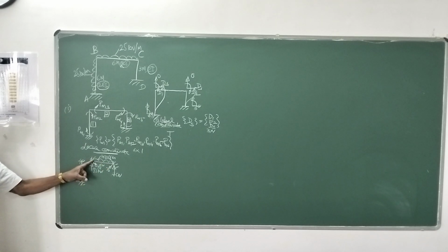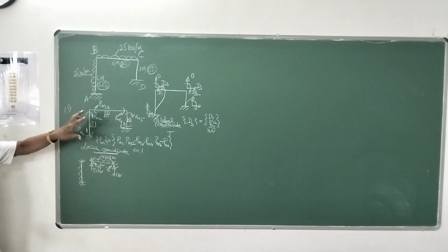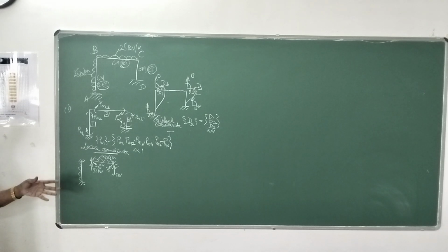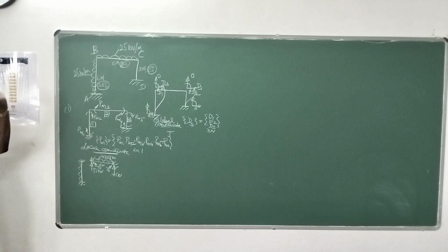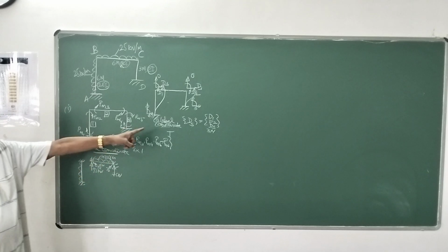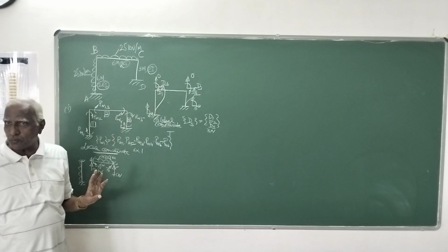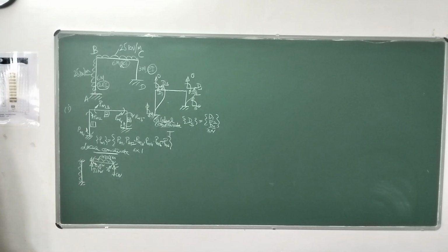So now we got the equivalent joint end reactions. So this reaction, you have to reverse its sign, as I told you in the beam problem. So here also we have to reverse its direction. That will be the equivalent joint load, and that equivalent joint load corresponding to these degrees of freedom, D1, D2, D3, we have to take as the global load matrix. So that is another exercise you have to do in this first step.